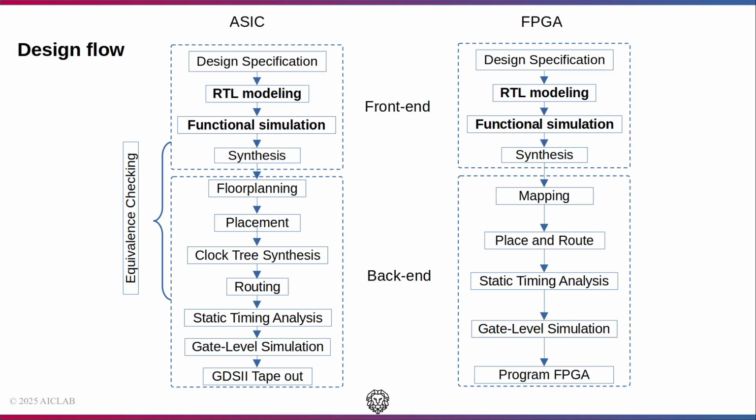Next is RTL modeling. In RTL modeling, we use hardware description languages like SystemVerilog to model or design. The next step is functional simulation. At this step, we want to verify the functionality of our design, and we don't care about the timing delay and potential timing violation.